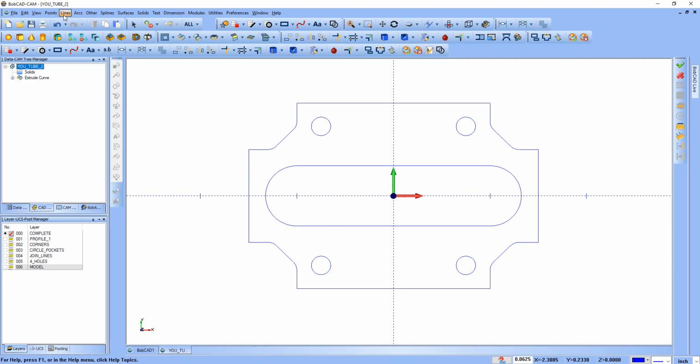And on here, you definitely don't have to do this. I like putting points in the center of my arcs to select when I run my drill cycle. You definitely don't have to. It's just, if you have a bunch of holes, it's nice because you can hide the rest of the stuff and just select all of the points, and just set your drill cycles up and run it, just like that.